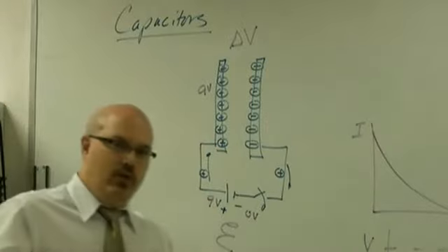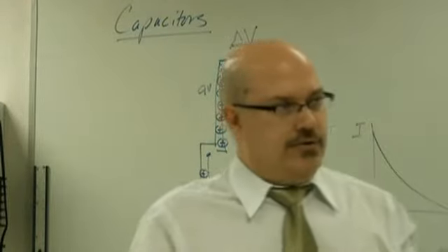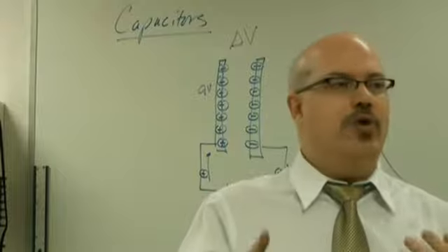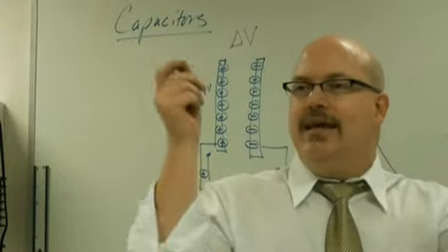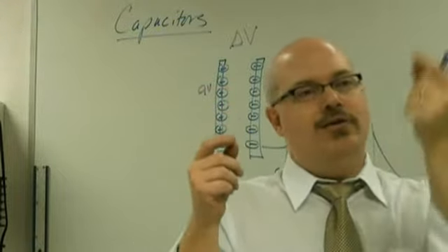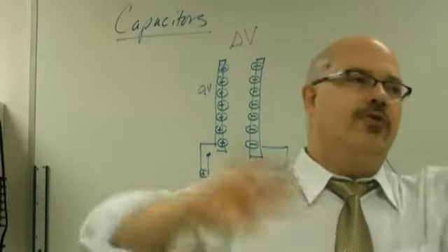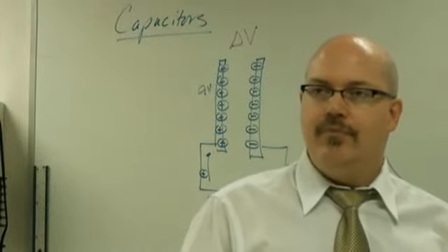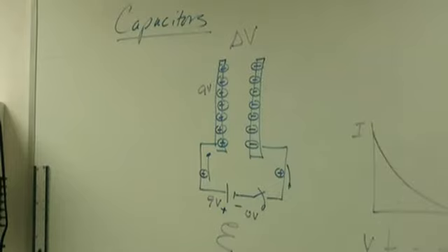Now, in the real world, capacitors will eventually drain out because a little bit of the charge will bleed across through the middle, or it'll bleed off to the atmosphere or something, right? But in this type of TV set, there's a big capacitor inside. So if we were to turn off the TV, open up the back, and touch both sides of that capacitor, it would be a bad day. Because there would be a popping sound and we'd take you to the infirmary.